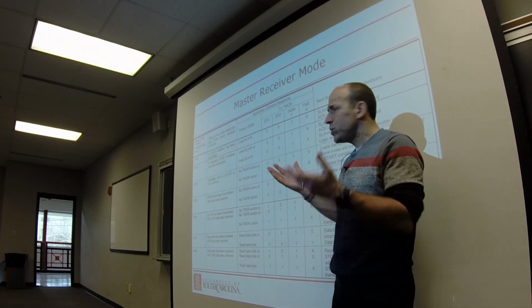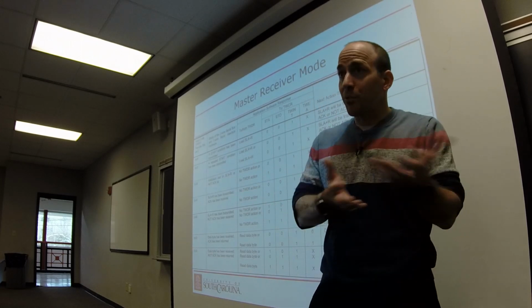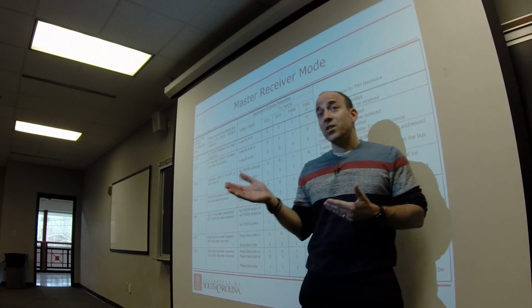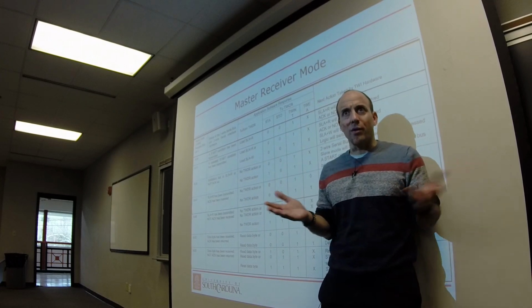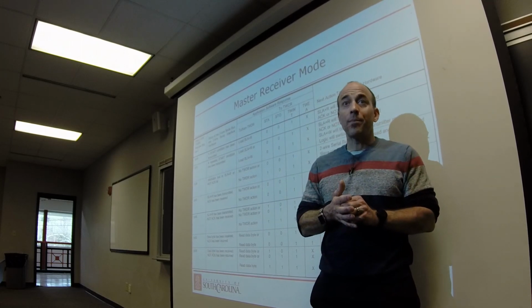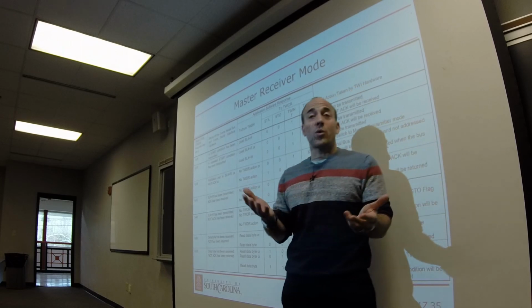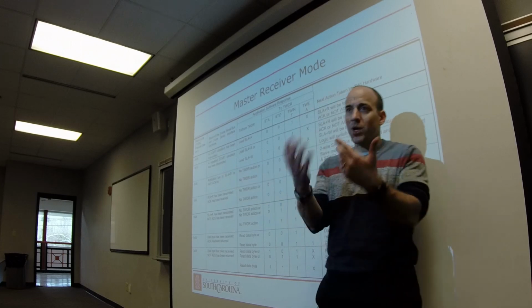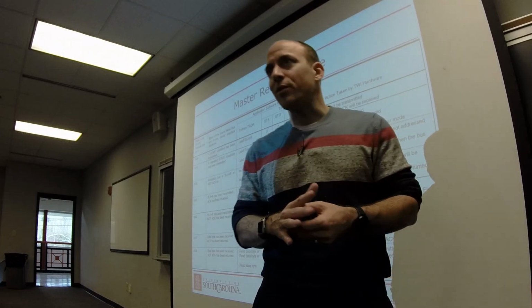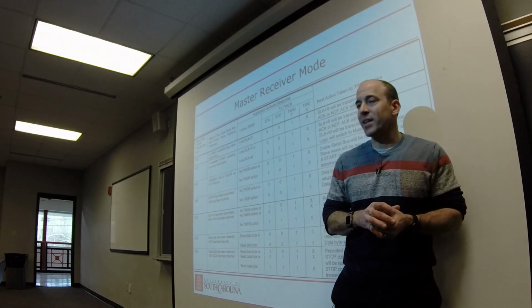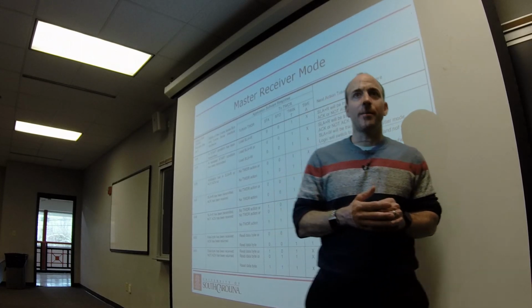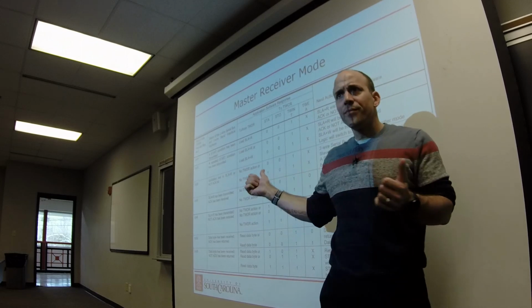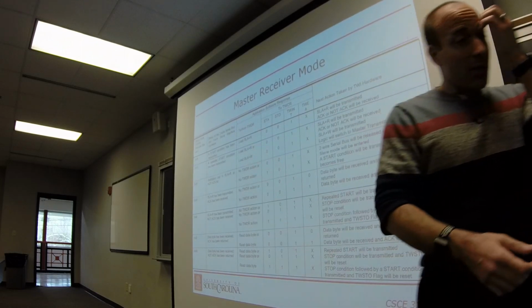So why would you use one or the other? Well, certain peripherals only support SPI, certain only support I2C. Some, like the accelerometer, I think support both. Right? You have the option. The other reason why you'd want to use one or the other is, in our case, we only have one SPI and one I2C, so we may want to use both just so we can talk to more peripherals. So, in fact, that's, I think, what we're going to do once we get the screen hooked up with the accelerometer. Any questions? Okay, good. All right, well, that's all the time I got.